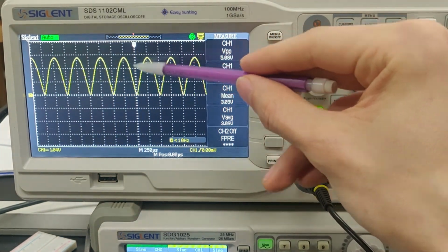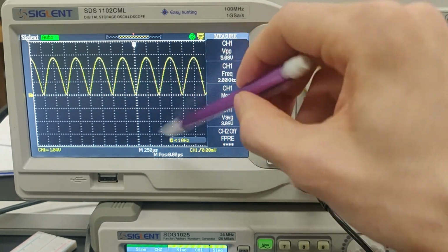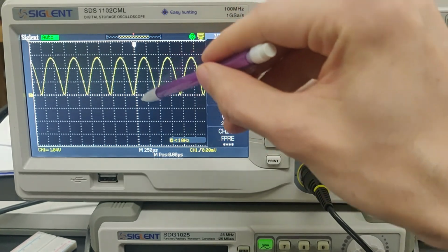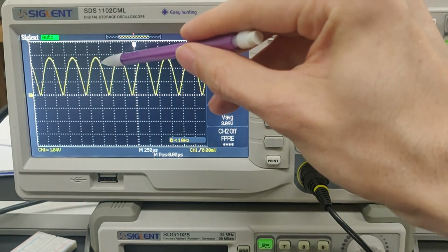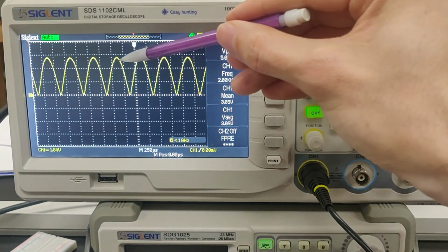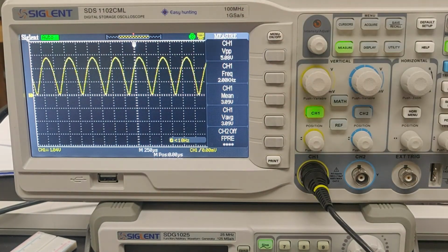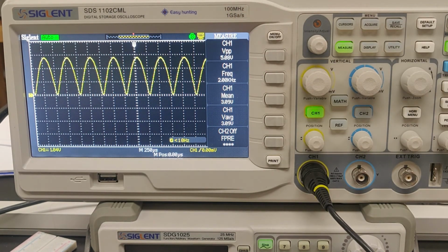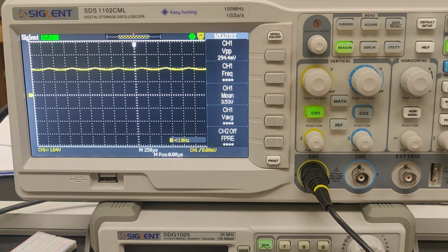So if you think about it, whenever we were doing the half bridge, it's like this middle one wasn't there. It was flat, peak, flat, peak, and so when we had to go from one peak to another, the capacitor had to bridge this gap. But now, with the full bridge, it only has to bridge this gap, which is half as far. So let me put it back. So now it's an even more efficient way of turning an AC signal into a DC signal.